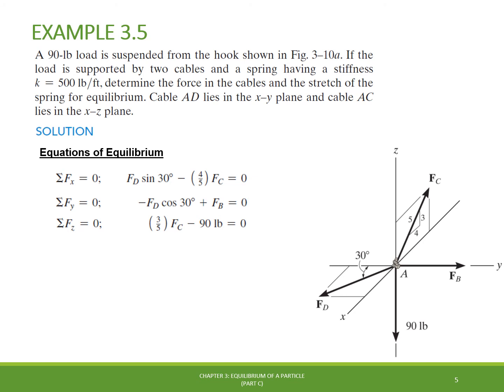Then we can solve those equations by simply playing with substitutions. For example, we can start by solving the third equation and get the force FC directly. Then we can plug the result of FC we just calculated into the first equation and get the result for FD. And finally, we take the result for FD and use it in the second equation to get the result for FB.